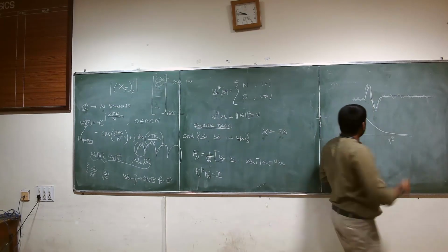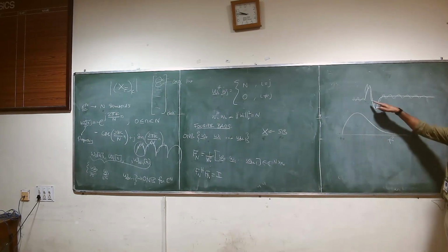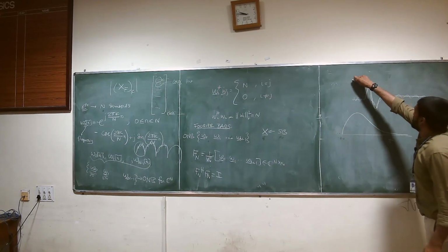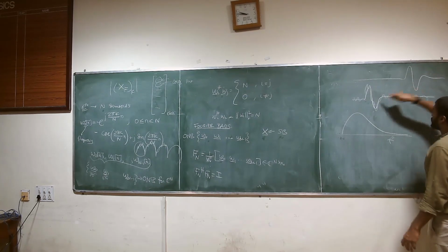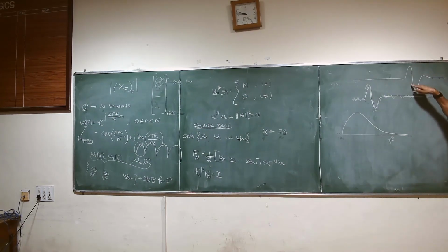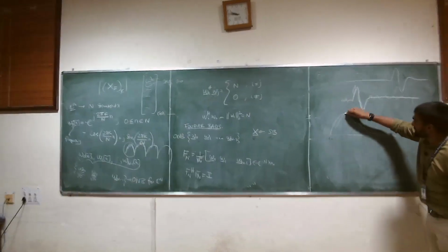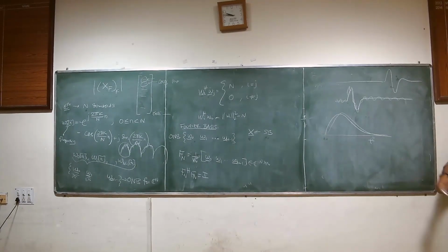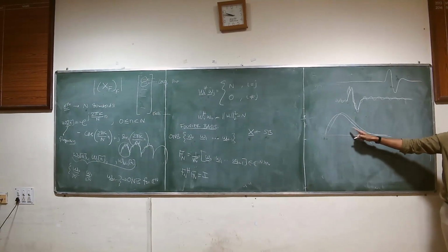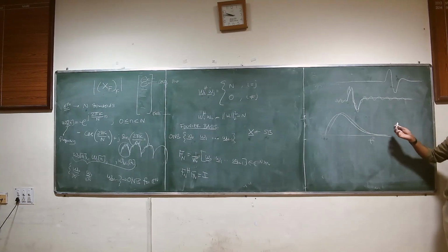In fact, the worst thing is, let's say you had one signal like this and another signal that is more or less similar, but time shifted. If you do the Fourier decomposition of this signal and you compute the magnitude of each of those components, you might get something like this. If you only go by the magnitude spectrum, you would say both the signals are the same, but clearly they're not.